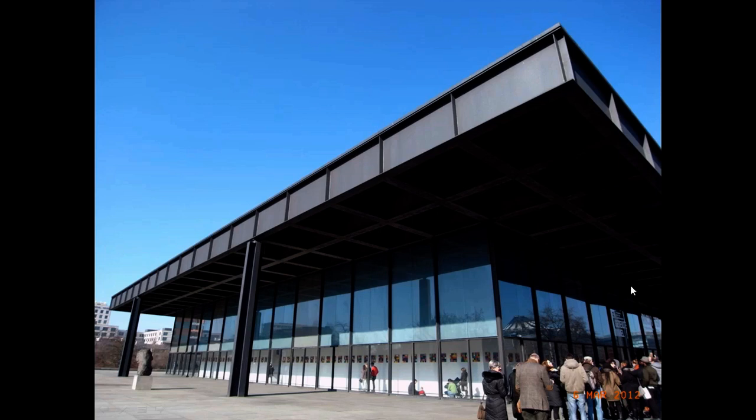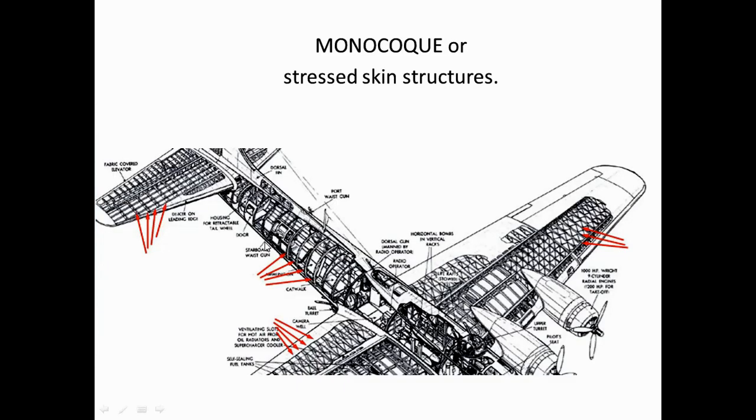Here all of this corner is cantilevering, isn't it? So that's what, 1, 2, 3, 4, 5 from the edge. 1, 2. So over here will be the next column, so you could triangulate that edge. That whole section is cantilevering. That's the beauty of this structure: you can pick it up anywhere, carry the load anywhere. You've got a continuous, effectively monolithic roof structure. This one was actually pretty heavy. I think, I may be wrong, they built that on the ground, hoisted it up and onto the columns.